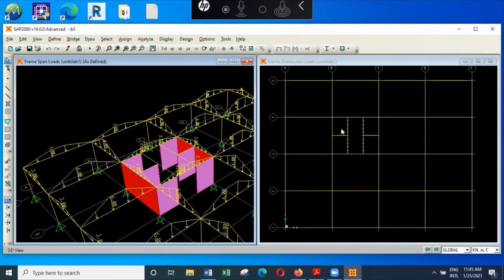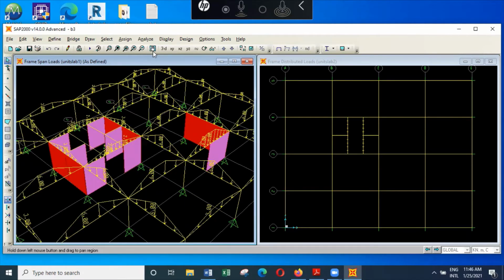But these will be voids. Other than that, we are not having voids. But here again, you might have a void where the staircase is located, so here still the loads will be transferred. That's why I have considered that. Some shear walls will be located in this area, and that is the area that we can easily use for a staircase.